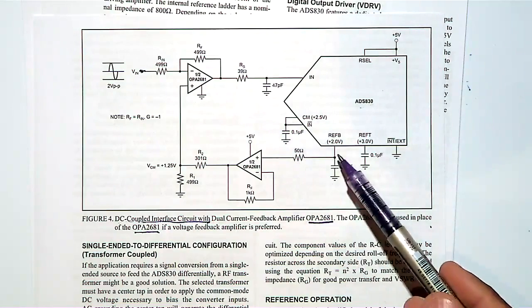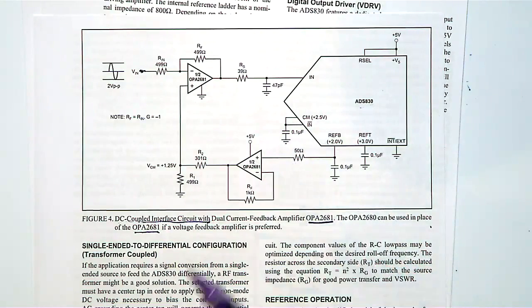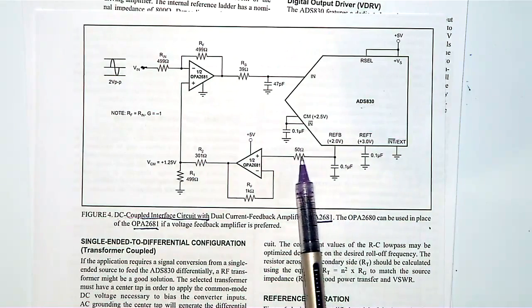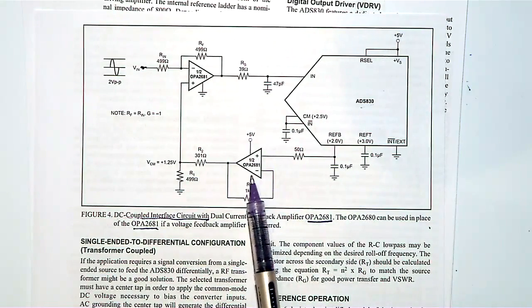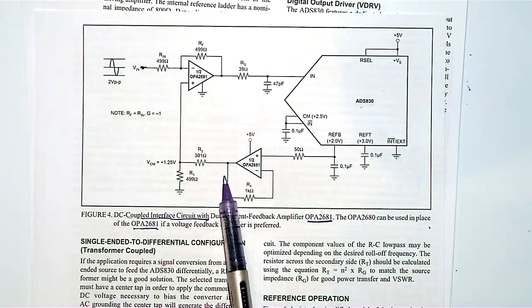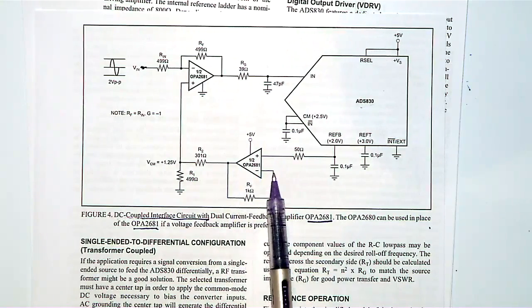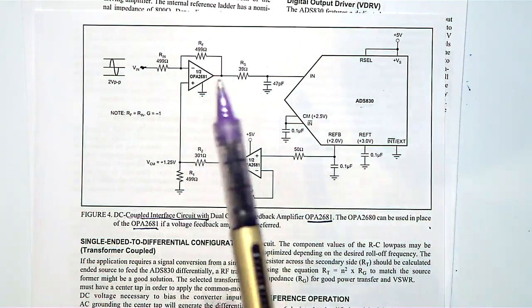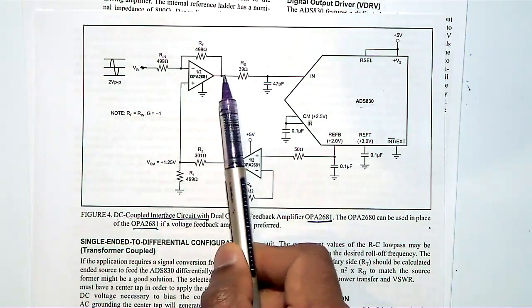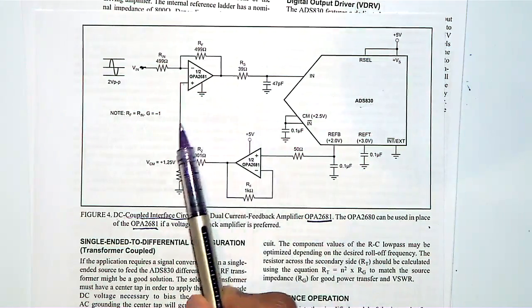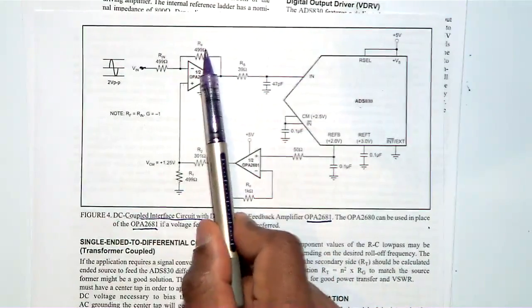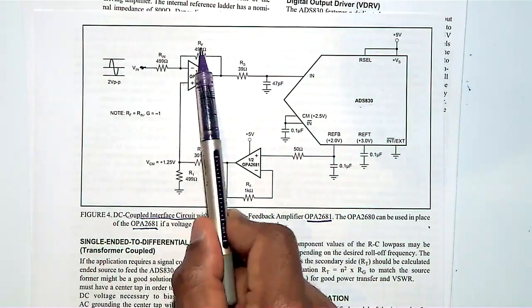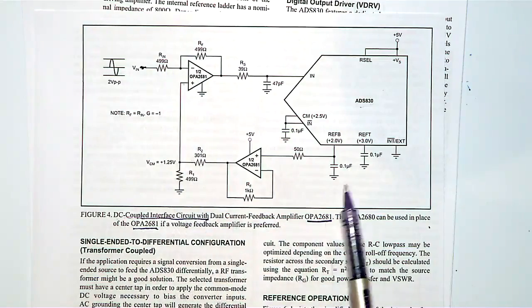And then here, when you look at it, they are connecting to the non-inverting terminal, and it is kind of a buffer. They connect the buffer, and from here it's generating some voltage, and that voltage is coming here. So this is actually a scaling network. But because this is operating in inverting mode, it is also an amplifier. So you can use this configuration.